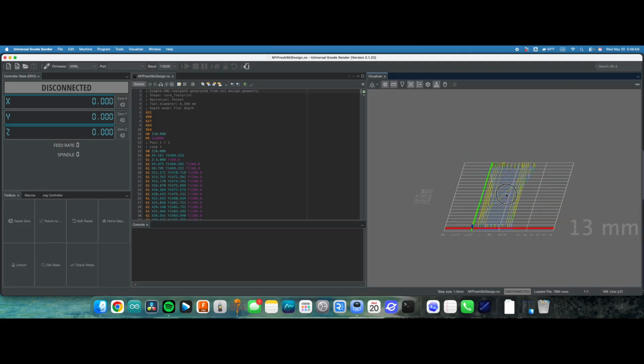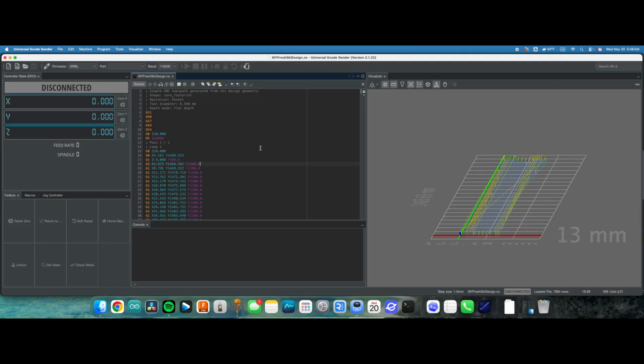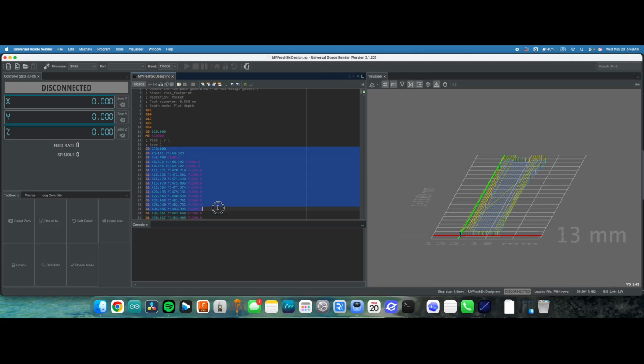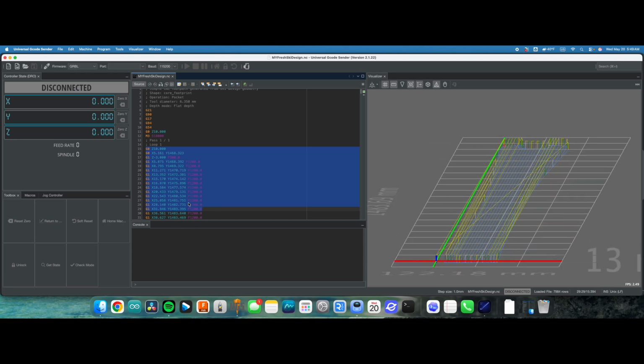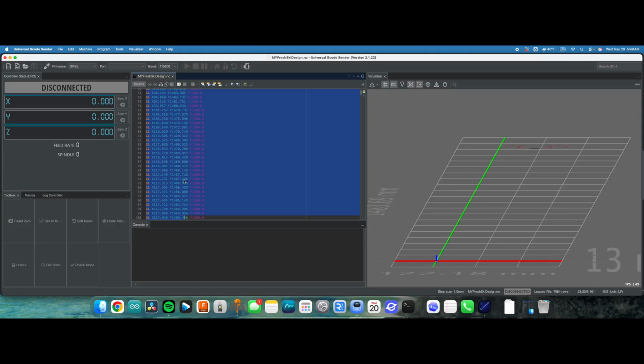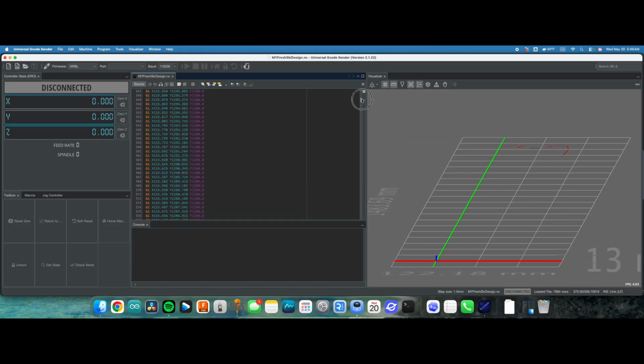My approach to this kind of sanity check is just to go row by row, inspect it for anything that I think looks unusual, any kind of weird typos or any grammatical errors. But then also, if you highlight it row by row in this software, it will highlight that portion of the toolpath in the preview pane over on the right. So I usually just go through and I hide all the toolpaths, and then I highlight down and just watch it go through the operation.